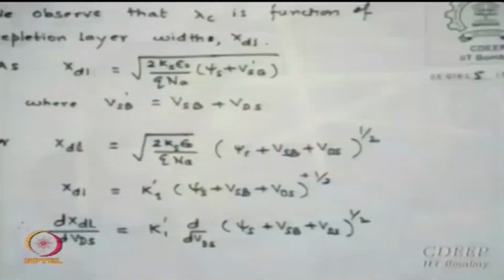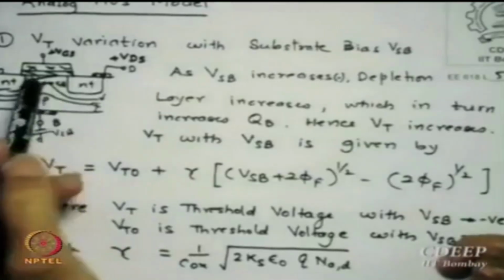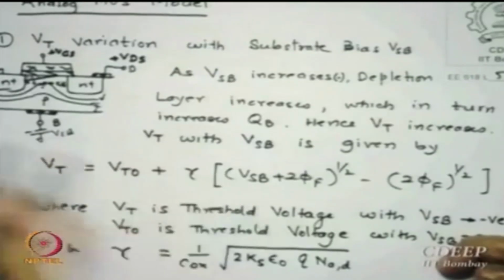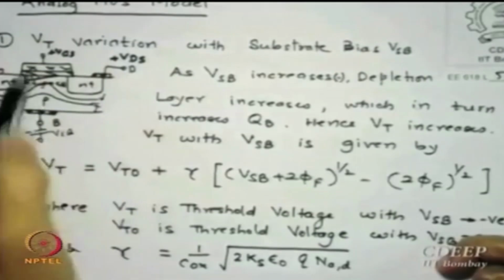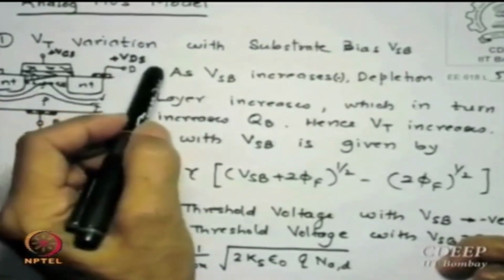The first one, let us see the lambda c part. If you see the expression of the transistor, or rather your figure of the transistor, just a minute, I will put that slide up again, but you can see from here, as I increase VDS, which is larger than VGS minus VT, right now let us say VSB is 0, even if it is there it does not matter, but VGS minus VT is much smaller compared to VDS.